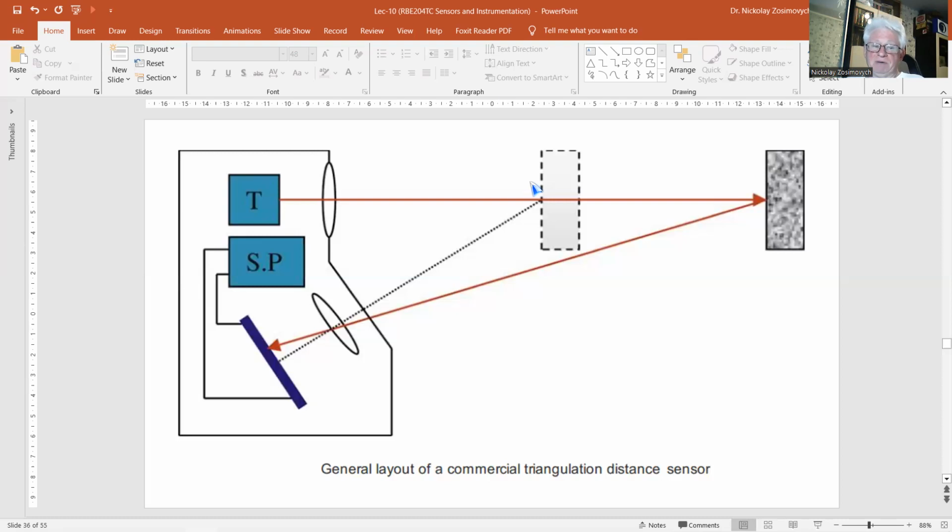An essential element of the system is a self-mixing interferometer, and this will be explained in the section on velocimeter. The system enables displacement measurements over a range of 500 millimeters with submicron resolution.